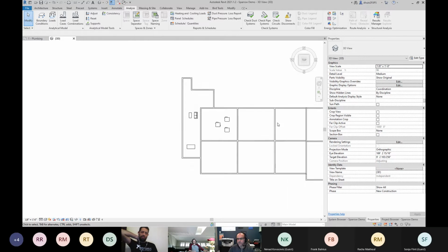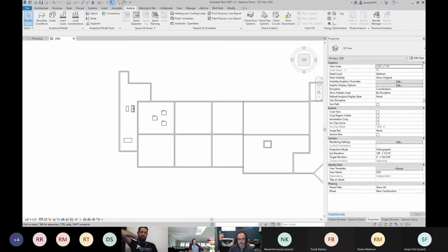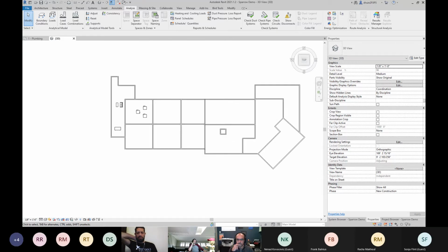So one of the universal solutions to that, because you might have a custom insertion family, it might be on the corner or anything, and you want your own ray bounce to go from the center. It's easier to get the centroid of the solid or the center of the bounding box of the element, so the insertion point doesn't really affect your workflow, but there are still always checks to be made and edge cases. So we're hoping through Sparrow to get feedback about any edge cases that might occur.